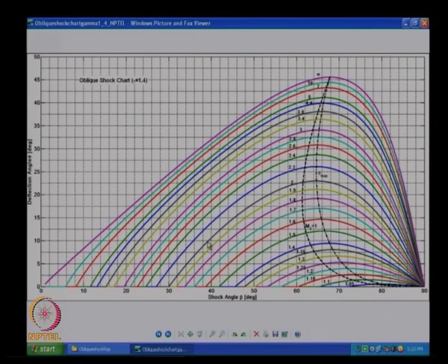So which means I am going to have two different shocks. Okay. I could have a shock that is having a low shock angle or a very high shock angle. First observation we are making. Okay. We will make more observations. I just wanted to plot this, I do not want to use this plot to explain things, I will go and draw this on the board and explain things. Okay. But one more thing to note, it has a peak value for every Mach number, and above that we cannot get a solution for beta. Okay. That is what you are having, and beta does not have a value below a particular Mach angle, below a particular angle, it so happens that it will become Mach angle, we are going to look at that now.